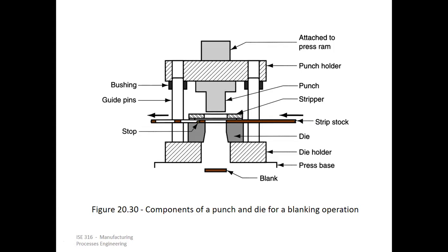You want to roll them, compress them, so that the dimensions decrease, the thickness decreases specifically, and therefore the grain orientation also changes. But those are dense now, and they are of lesser thickness, the thickness that we want. So that sheet is fed in the form of a strip. Basically, that sheet is fed, and then this punch is responsible for cutting out material from that strip.